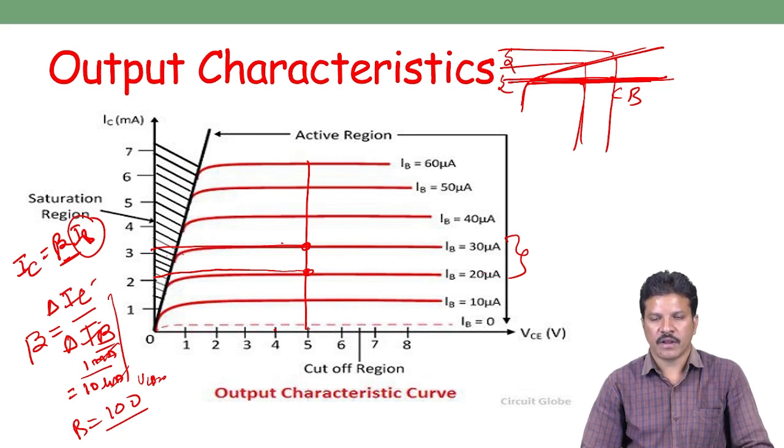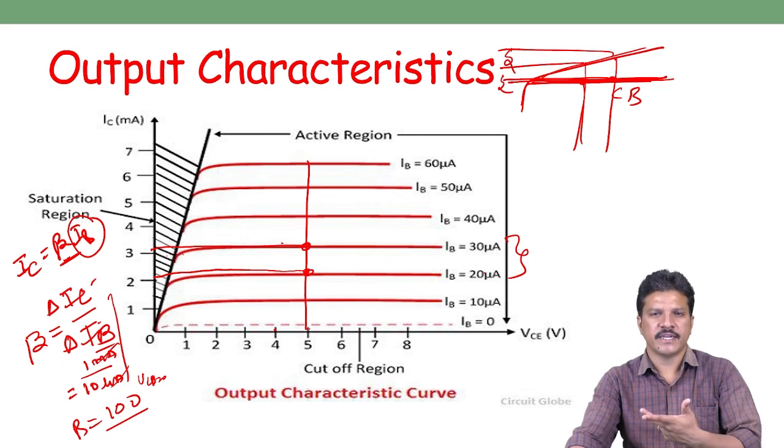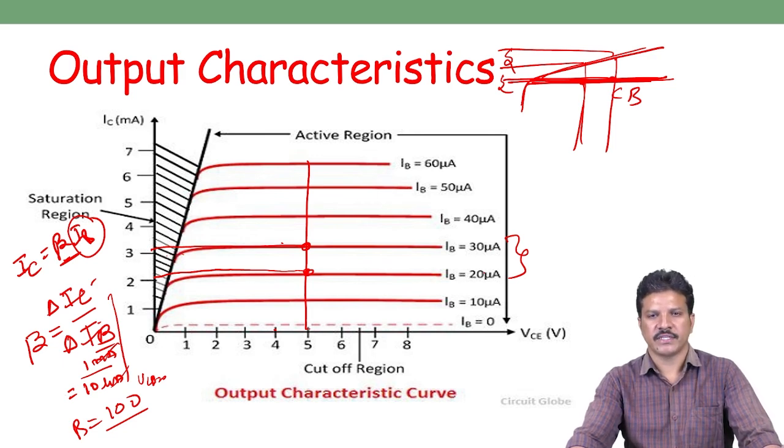So the main purpose of the common emitter configuration is that it is useful for an amplifier at an intermediate stage. For op amps, for example, with an input stage, an intermediate stage and an output stage, we always prefer the common emitter configuration at the intermediate stage. In the input characteristics, the cut-in voltage is 0.7, the input resistance is low or medium, the output resistance is medium, and the current gain is very large.